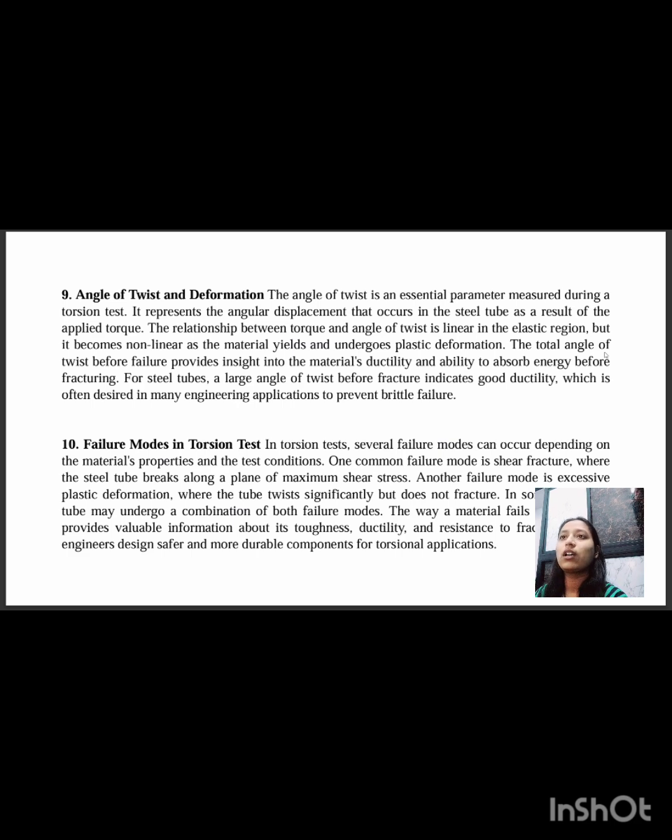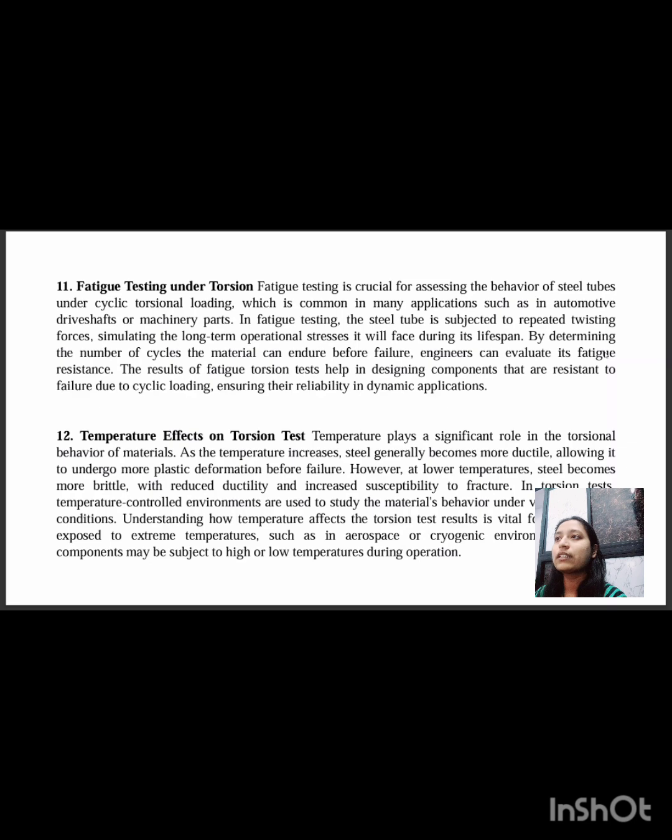So next, fatigue test under torsion. It is assessing the behavior of steel tubes under cyclic torsion loading, which is common in many applications such as automotive drive shafts or machinery parts. In the test, the steel tube is subjected to repeated twisting. The number of cycles the material can endure before failure is recorded.